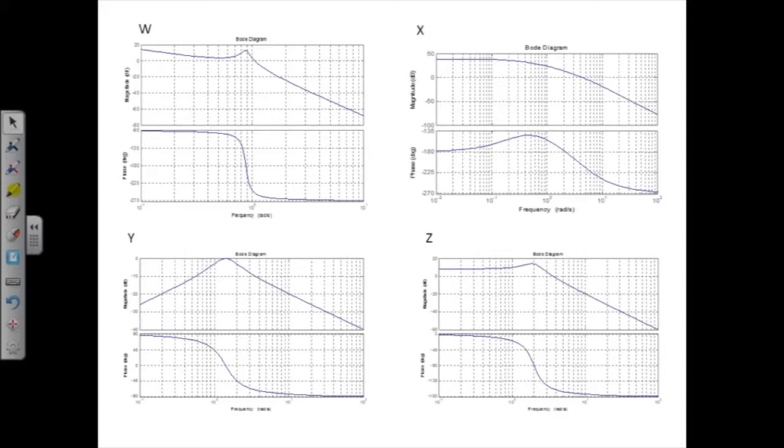Would it be because the phase... I changed my mind. Something to do with 90 degrees out of phase, and that's what a differentiator does. Okay, was that what you were saying at the front? Yeah. It starts off with positive 90 degrees of phase shift, doesn't it? And the only thing in the recipe book that gives us 90 degrees of phase shift right from the start is a differentiator.